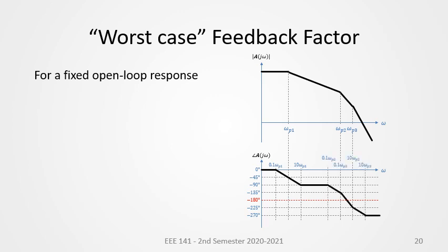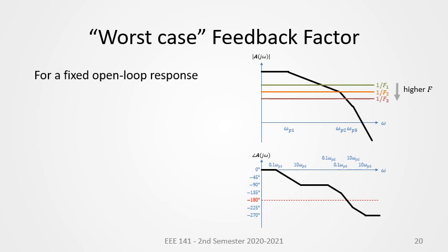However, the second and third poles are quite near each other, and thus there is a portion where the phase shift contributions overlap, and we get a middle portion with a minus 90 degree per decade slope. As a whole, having 3 poles at the left half plane, we expect that the total phase shift should approach negative 270 degrees. Now, let's take a look at 3 cases for the feedback factor f.